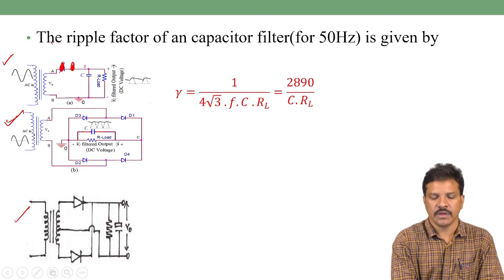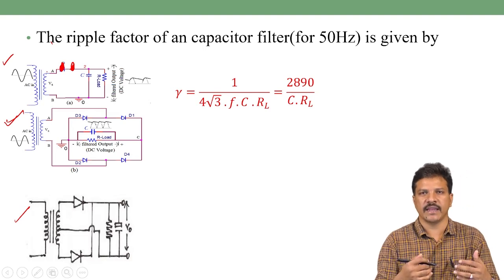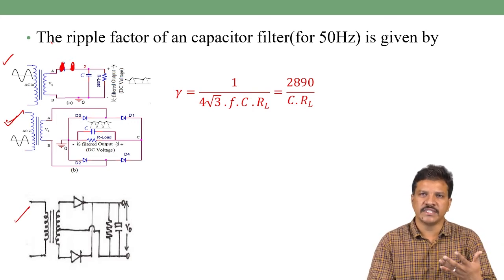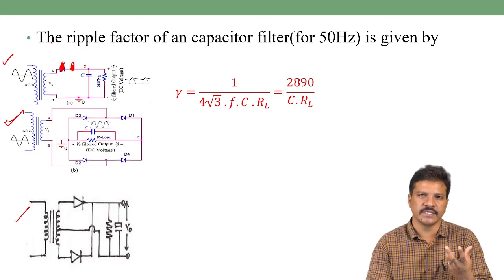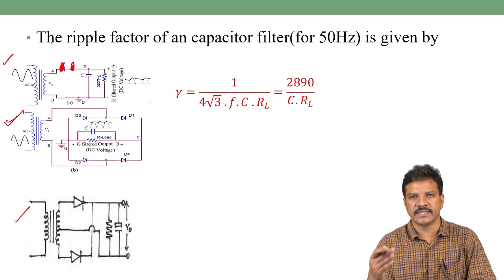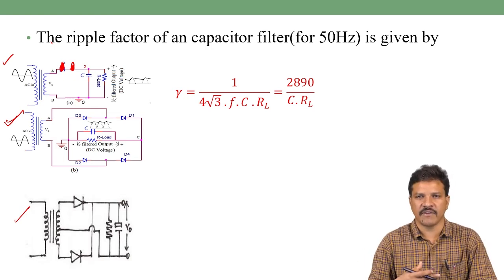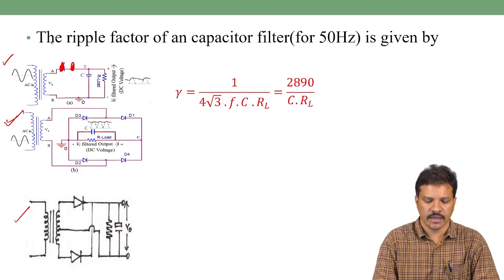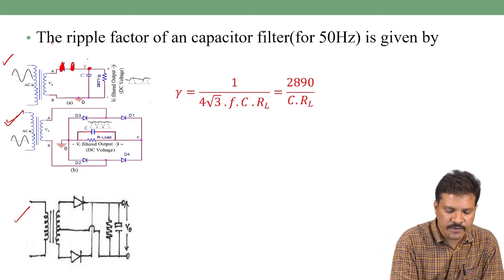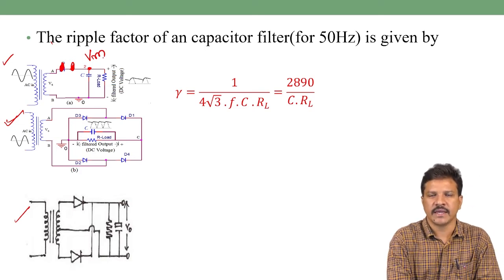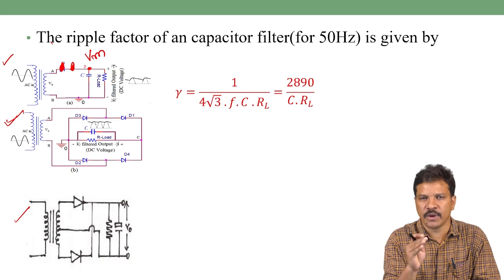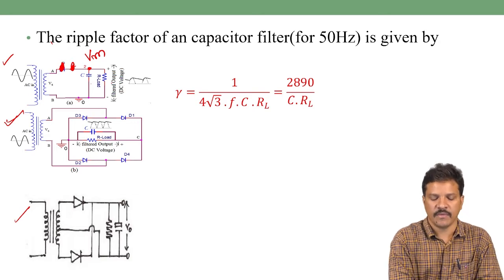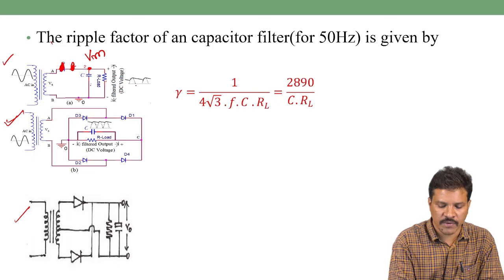When it is open circuit, there is no connecting path to charge again, but the capacitor is connected to the load resistor. The property of a capacitor, once fully charged and storing some voltage, is that whenever a low resistance path or load resistor is connected across it, it has a tendency to discharge that energy through it. So up to the maximum voltage, it charges to Vm. When the rectified output voltage falls just below Vm, the diode disconnects and the capacitor is connected to the load resistor, so it starts to discharge.